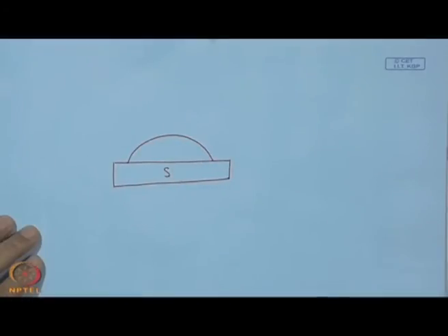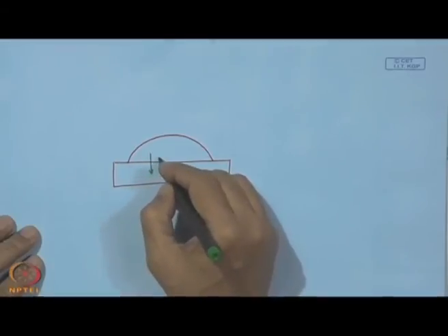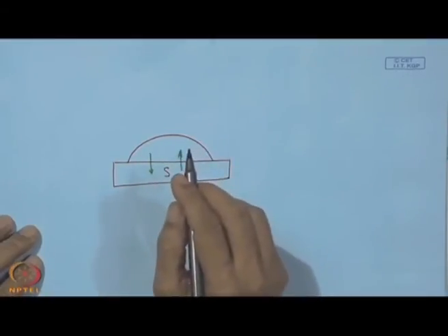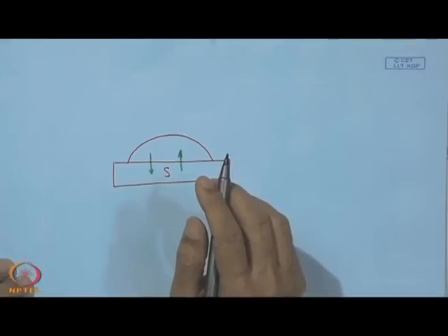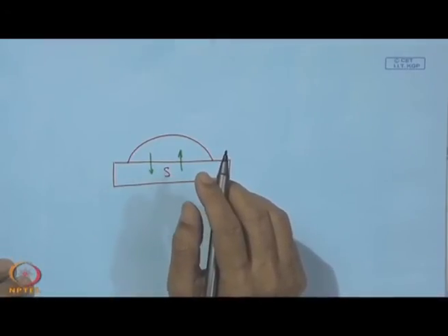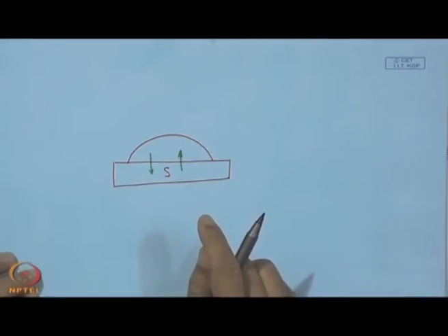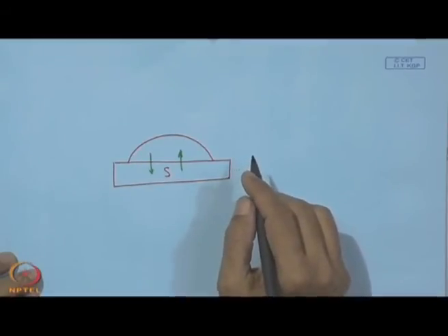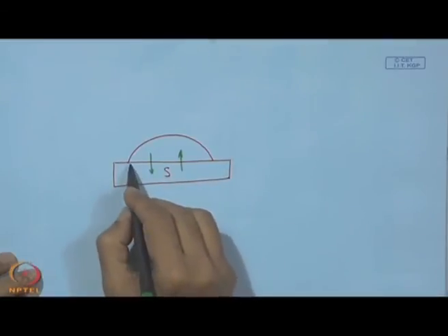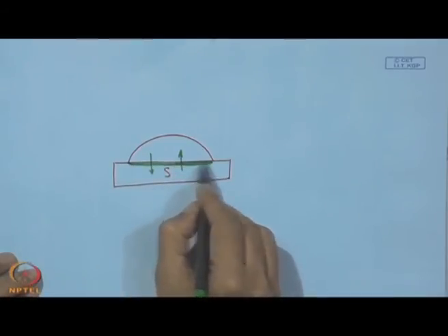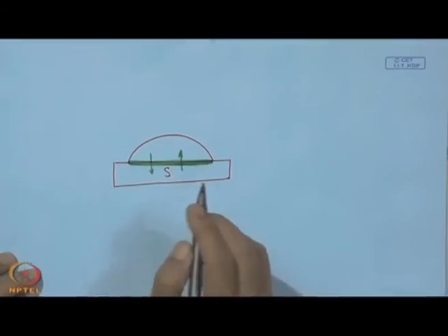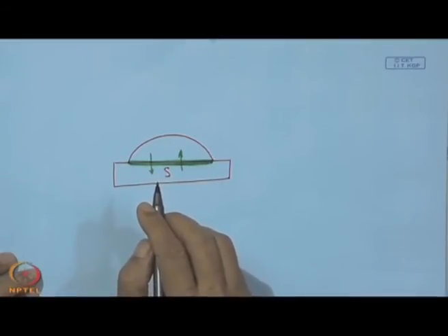More importantly, here you have transfer of the material either by the process of diffusion or by chemical reaction or alloying at the interface. That means there is a chemical bridge established at the interface, and as a result it is no longer a two-phase system, but it becomes a three-phase system. So, you have here a diffusion layer or a reaction layer or a layer because of the alloying.